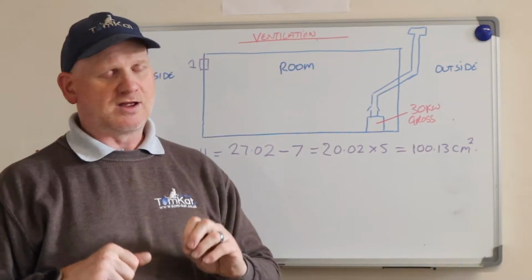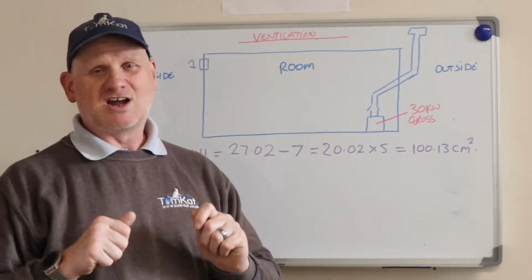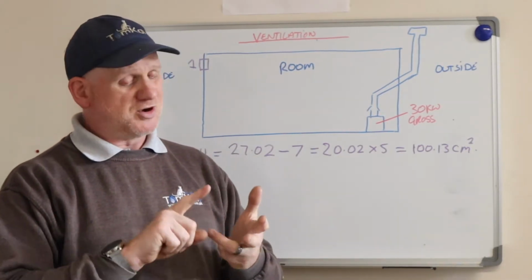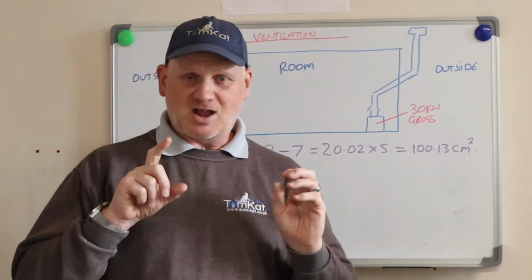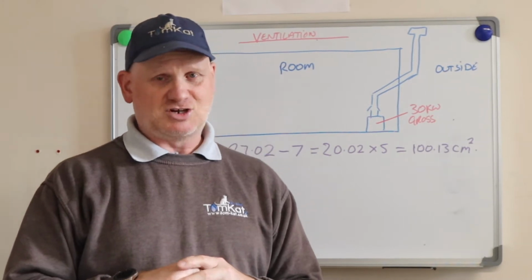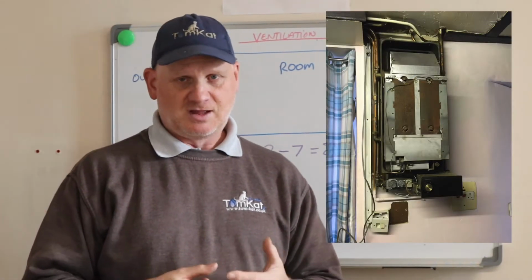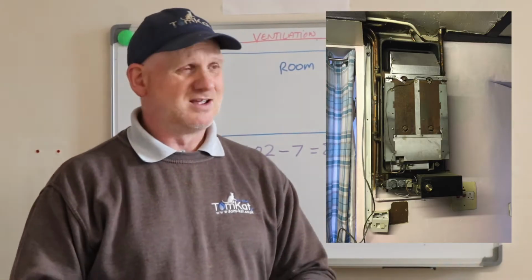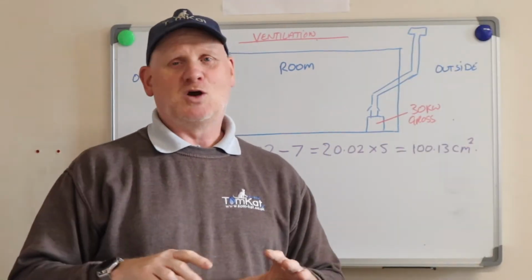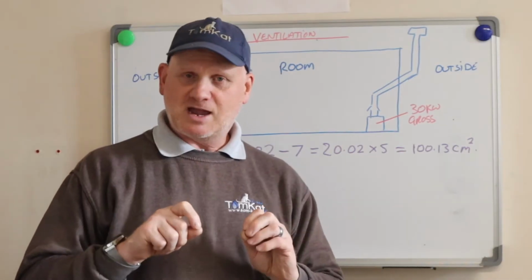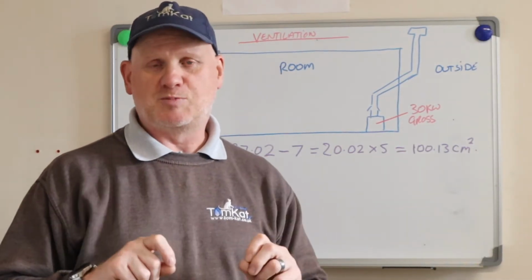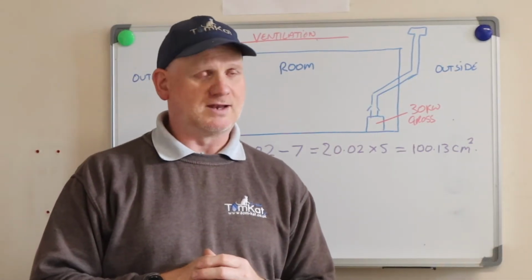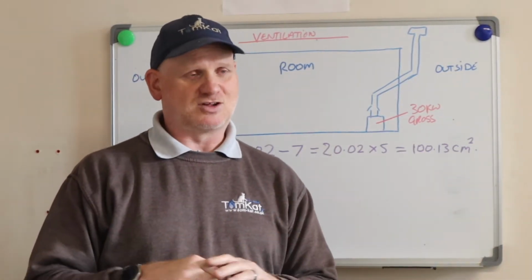So no boiler in the UK market requires ventilation, whether it's installed in a room, a cupboard or a compartment, because they also don't need ventilation for cooling purposes like the old cast iron heat exchanger boilers required in the old days. So no boiler in the UK market requires purpose provided ventilation for combustion or cooling in a domestic situation.